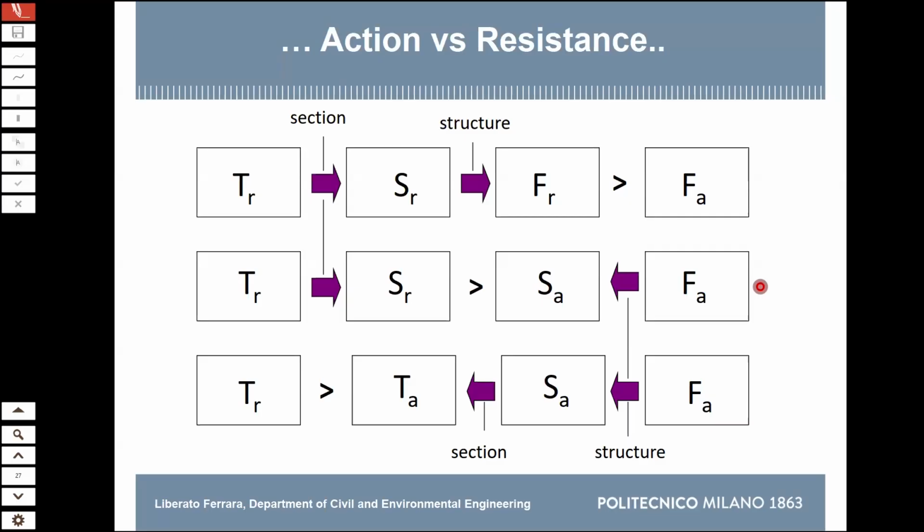So this means that you perform a structural analysis model and a section model, and you perform your check at the level of stresses and strength.